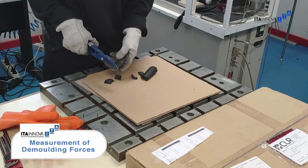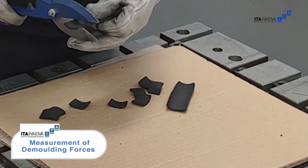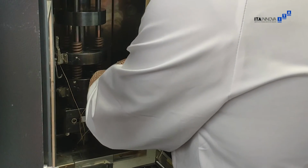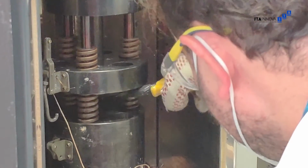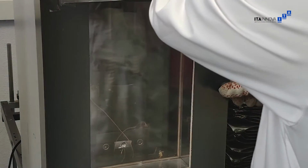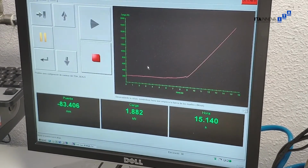After the uncured rubber material is prepared, the demolding process is analyzed experimentally at laboratory level with laser-textured mold samples. The experimental setup intends to replicate mold transference with the capability of measuring demolding forces in the most unfavorable situation. A universal testing machine is used and specific test fixtures inside a climatic chamber are employed.